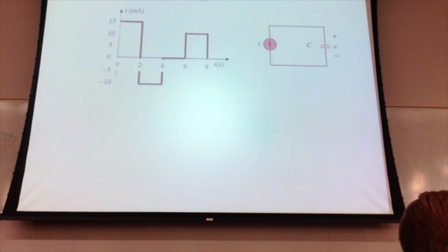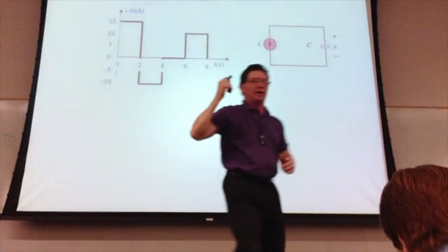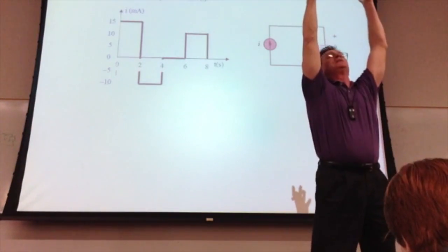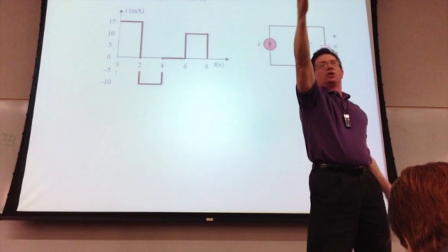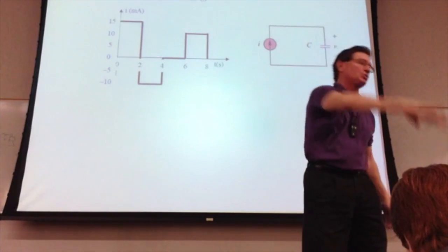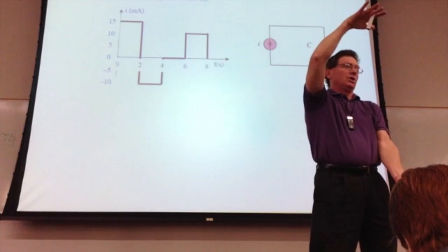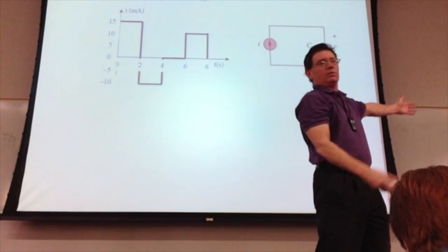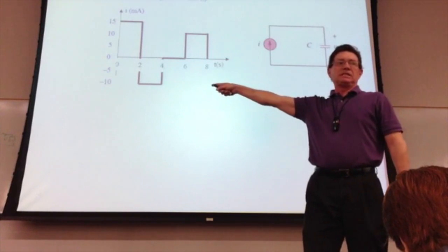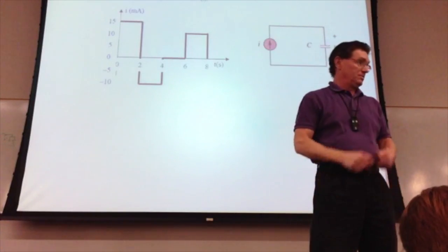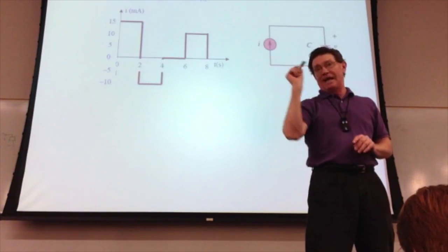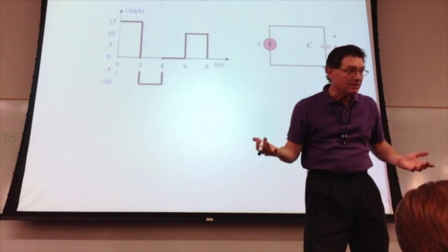What this allows me to do is, based upon what these two turn ratios are, I can step this way up. So if I'm sitting at my hydroelectric power plant, I put a transformer there, and I step those voltages 50,000 volts, way up. Then I transmit it all the way down to your little house. Sitting outside your house is a step-down transformer that takes that high voltage, collapses it down to 110, which is coming out of your wall. You can't do that with a DC system. You can transmit the energy, but you can't transmit it very far. Mr. Edison built his first dynamo system in Manhattan. Why Manhattan? Why would you think?